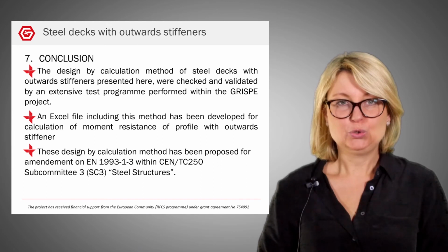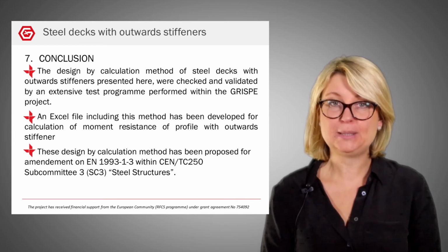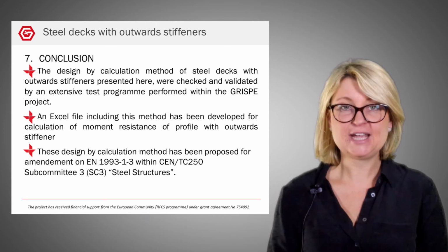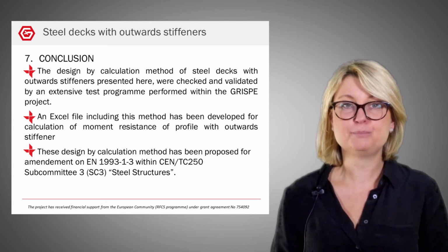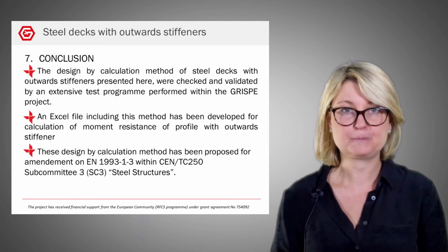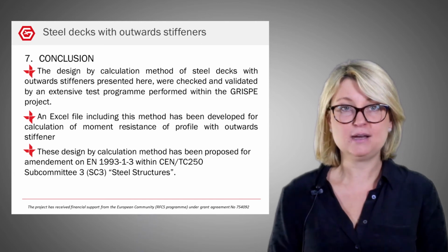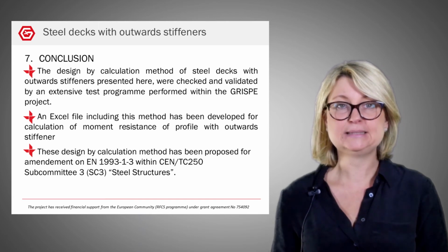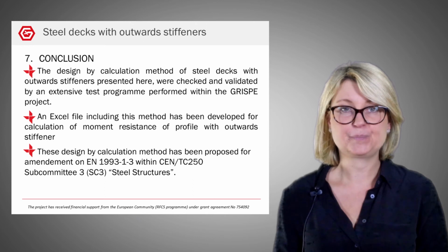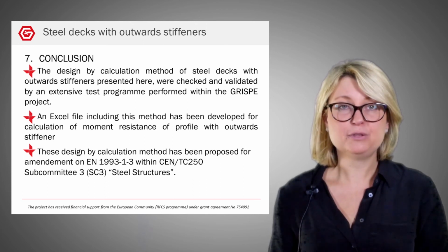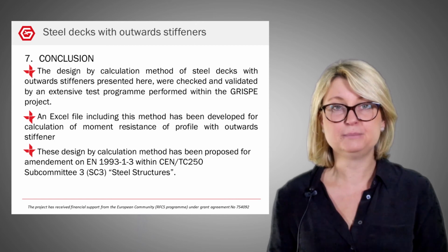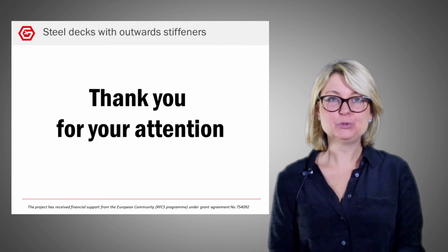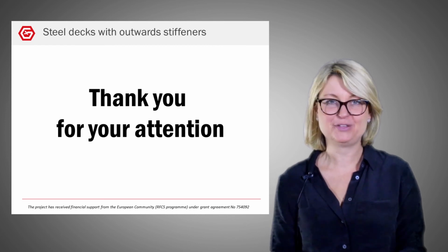To conclude, it is important to underline the following points. This design by calculation method was supported, checked and validated by a huge testing program performed within the GRISP project. Secondly, an Excel file was implemented to calculate a span moment resistance for steel decks with outward stiffeners. Lastly, this methodology was proposed for amendment on Eurocode 3 part 1-3. I hope I contributed to making you more familiar with this methodology.